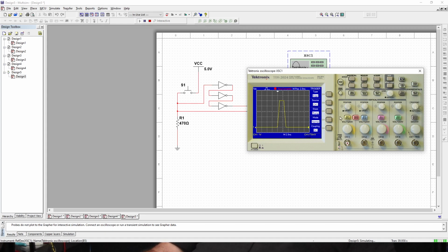But what we can do is click. There's a button that says Measure. All right, so we can click on that, and notice the soft menu here is going to change. So click Measure. We're measuring channel 1, and it says None. What happens when we click source channel 1? Let's click Measure again to bring it to that point.